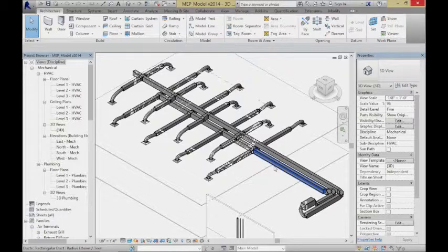What I'm going to guess by looking at this is that this duct system, the one that's heading out here, is probably the supply system. I tend to supply the conditioned air out to the outer boundary of the space. Again, that's where it's changing the most.